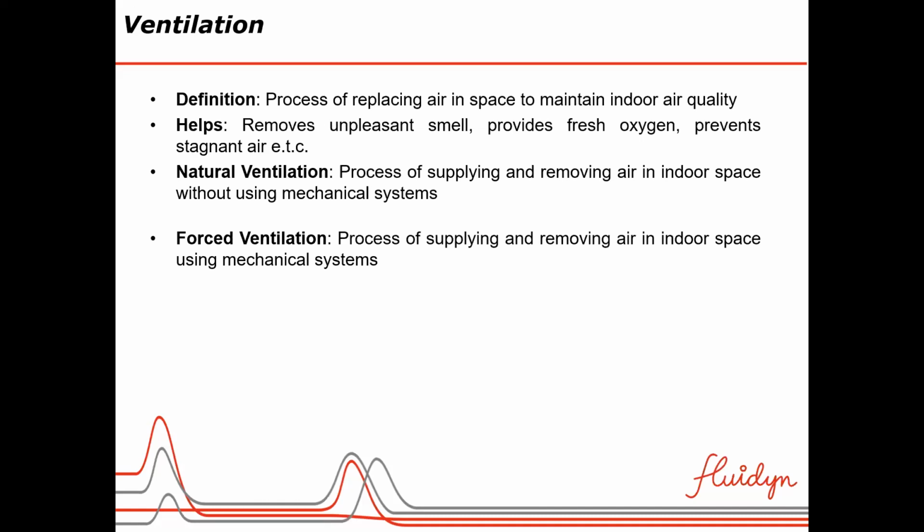We have two types of ventilation. Natural ventilation, without any mechanical systems, changes and replaces air by providing windows, doors and other openings. The other is forced ventilation, a process of supplying and removing air with the help of mechanical systems like blowers, etc.